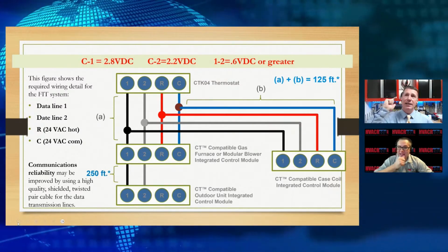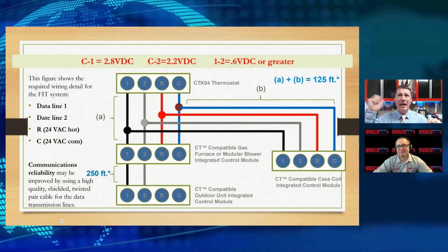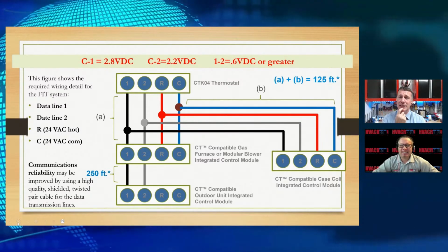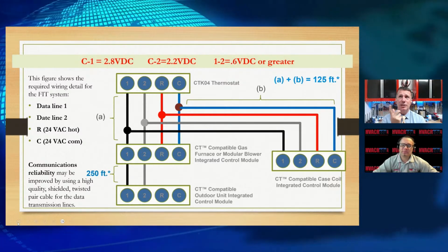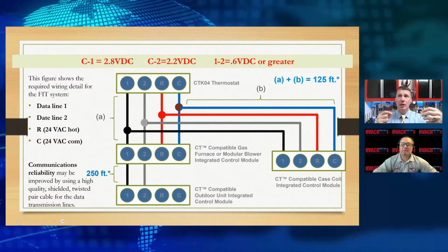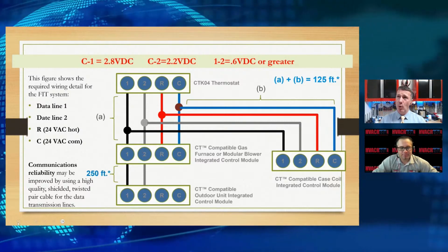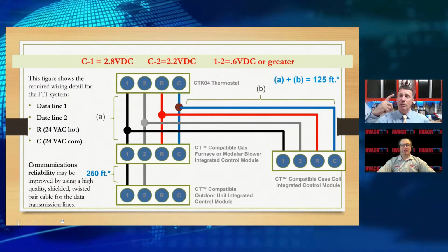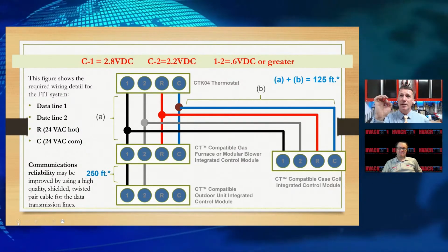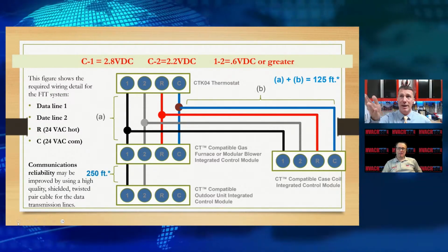So I had a technician that called me and said, "Hey, I've got good bias voltage at my indoor, at my thermostat, and my EEV. My outdoor unit, I've got some janky voltages and my bias is not right." I'm like, "Well, that's really interesting. Let's check your voltages to ground," and they were low at the outdoor unit. So I had him disconnect the wires from the outdoor unit and check the wires going to it. The wires were good. As soon as we connected it to the outdoor unit, the voltage dropped. And I thought, well, maybe it's a board, or is there something else? Let's go check all of our ground. We found a corroded lug inside of the disconnect that had poor connection. So the path could not make it back through the electrical panel to the indoor unit. The reference point was bad.